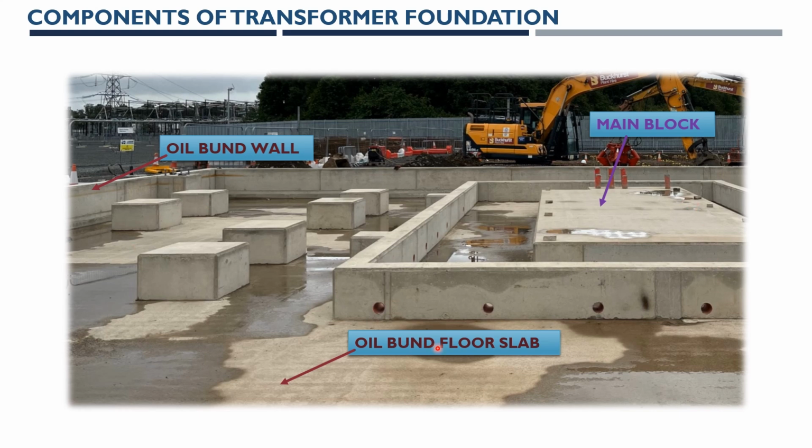In this whole area, the oil is to be stored when there is a leakage or burnt oil spill from the transformer. These are the accessory supporters, as we have looked at, cooler supports and the ladder; any accessories that need supports should be provided.